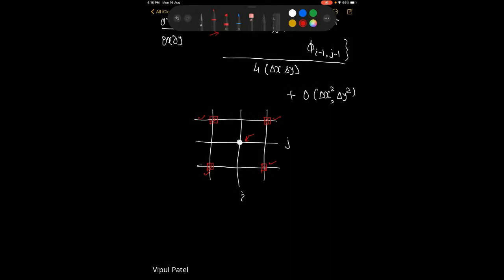And this might be an issue for the stability of the overall iteration process. Because of that, people say that these mixed derivatives are always challenging, because your iteration, or you can say your convergence, may be affected by the non-participation of node ij. So we must have certain formulas where a contribution from node ij arises. This will improve the rate of convergence of the overall iterative process, because we normally use the Gauss-Seidel method, some iterative process, to converge the results, right?